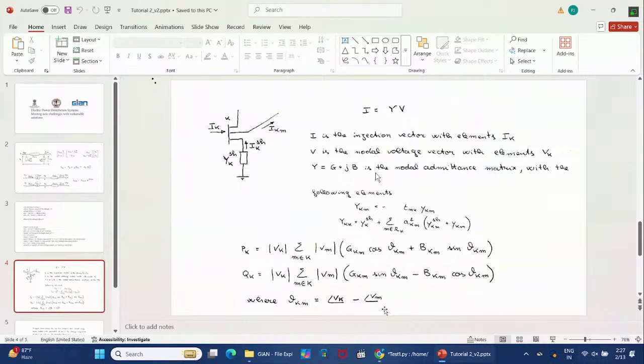So we write this equation because we want it to give P load in the receiving bus. And we write this equation in order to have 0 reactive power in the receiving bus. So our equations are indeed the difference between this equation and the set value. And fsolve finds the 0 of this difference. So it takes this constraint as equality.